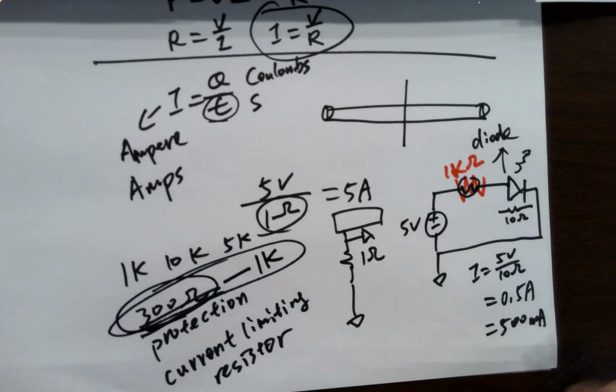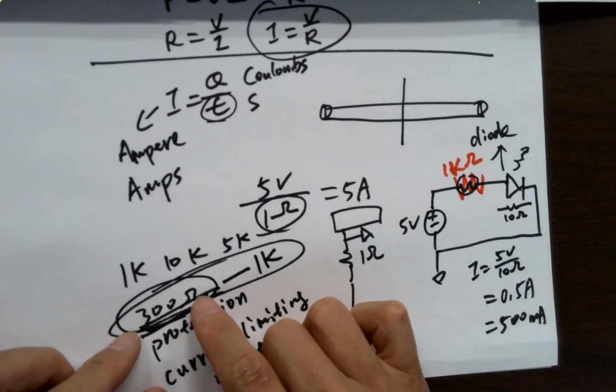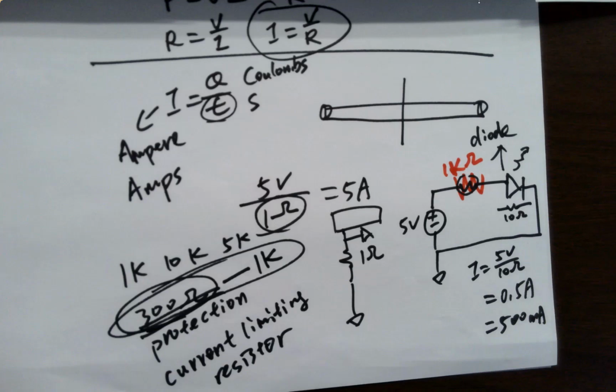If you grab a 50 ohms resistor, should I blame you? Before taking this class, yes. After taking this class, no. Oh, the other way, actually. Anyway, nothing below 300 ohms for digital stuff. Just grab a 300 ohms, 500 ohms, 800 ohms, 1K. It's okay, all of them are fine. You can always adjust it if it's too dim or too bright. Usually they will be fine.